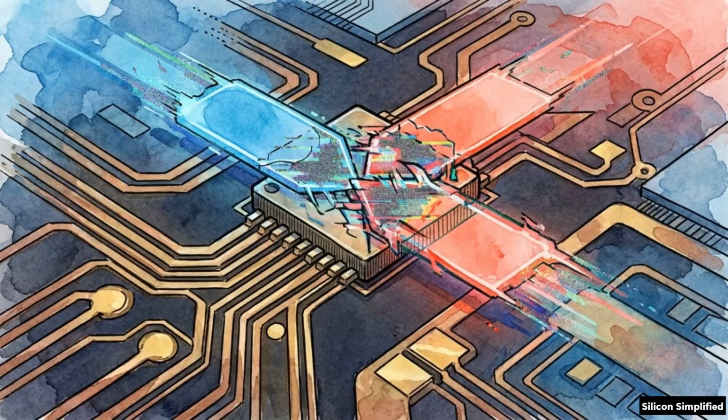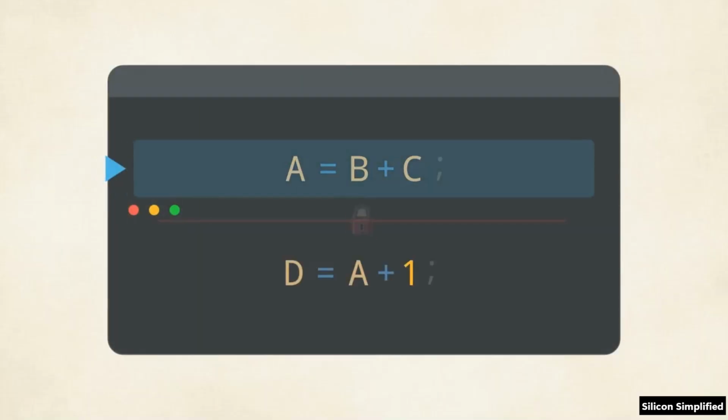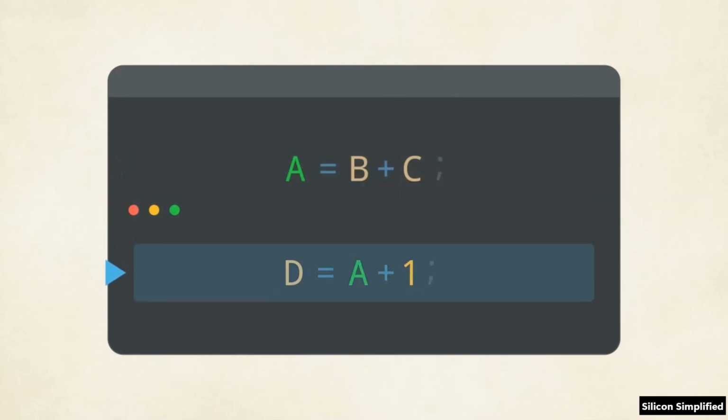Even with strict block statements, engineers thinking in C often trigger race conditions when they assign data to variables. The culprit is usually the standard equal sign, known in Verilog as a blocking procedural assignment. A blocking assignment calculates the right-hand side and updates the left-hand target immediately. It physically blocks the execution flow, preventing the simulator from reading the next line.